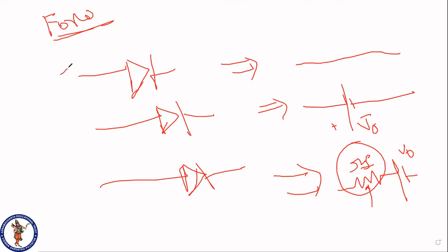The reason why I'm telling is that sometimes they will mention in a circuit a diode and they will give the built-in voltage and the resistance and everything. We can replace it with the normal input voltage and resistance. It will become a simple circuit with a voltage and resistance, so that we can calculate it very easily using some of the theorems or some of the techniques based on network theory. That is the reason why we are using this analysis.